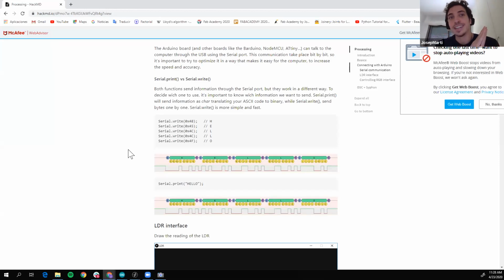Serial communication can be tricky to read. If you use Serial.print, you can have different characters there that can mess up your reading. If you define a protocol of communication, it's always easier and more stable.